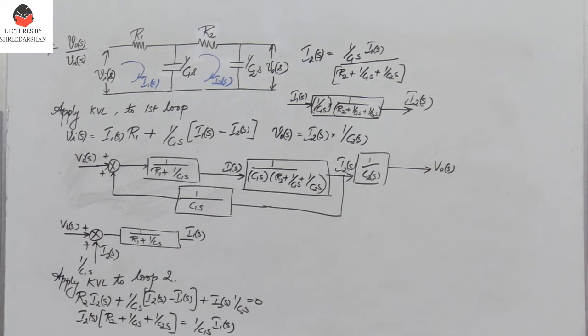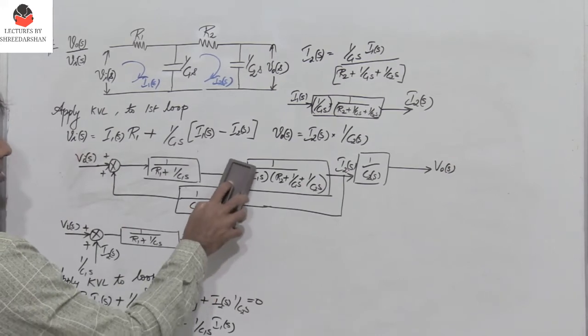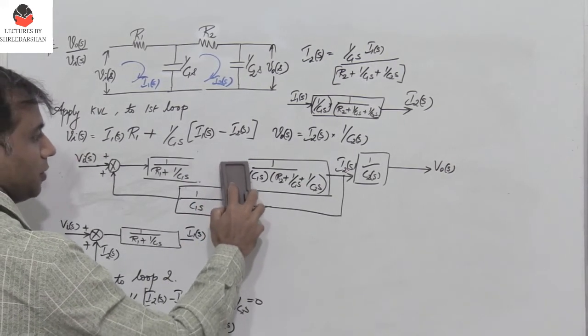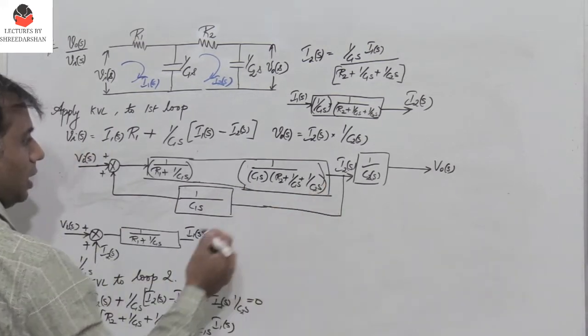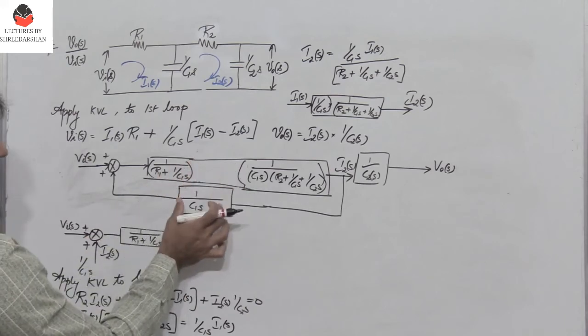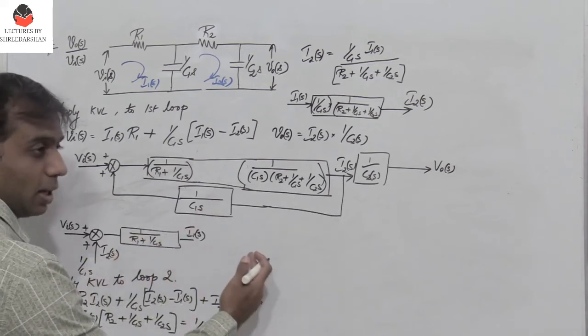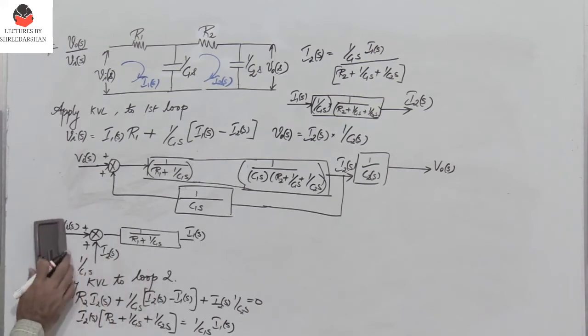So the first thing is, of course, these two can be multiplied because they are connected in series. So I would get this expression, this transfer function into this. So I can just multiply these two. And then if this is G of S and this is H of S, I have a plus sign here. So it's going to be G of S divided by 1 minus G of S H of S. So let me do the feedback path.